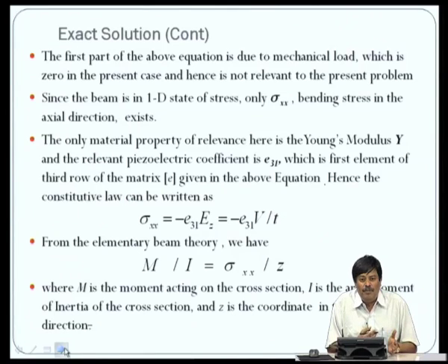The only material property of relevance here is the Young's modulus Y, and the relevant piezoelectric coefficient is e31, because it is in direction 1 due to the field in direction 3, that is the z direction, which is the first element of the third row of the matrix e. Hence, the constitutive law becomes sigma xx equals e31 into Ez, or e31 into V by t, where V is the applied field in the z direction.